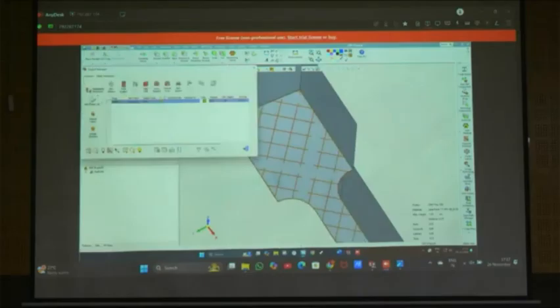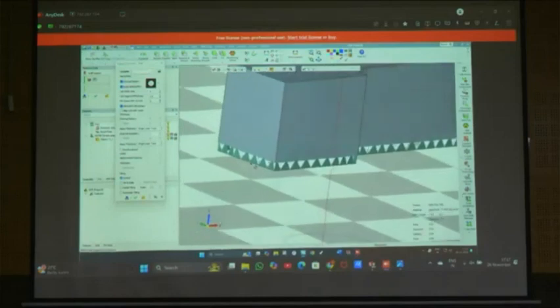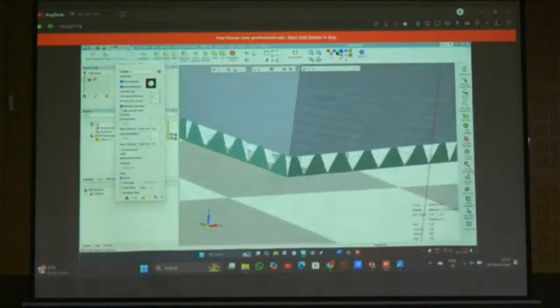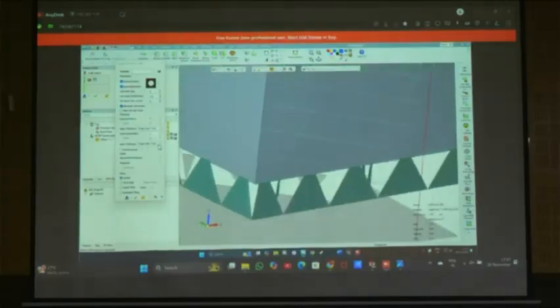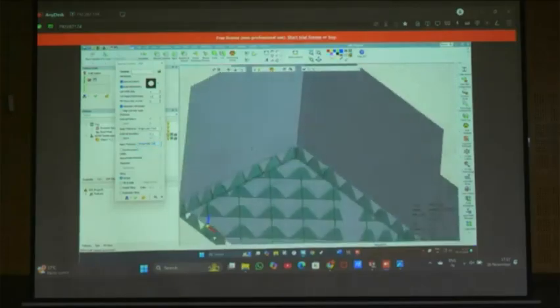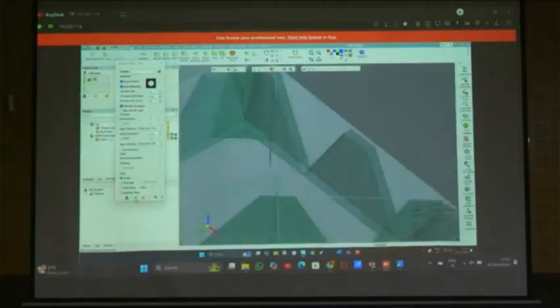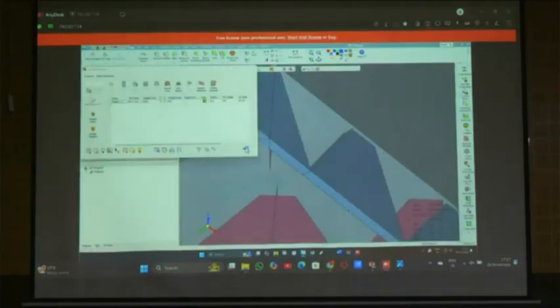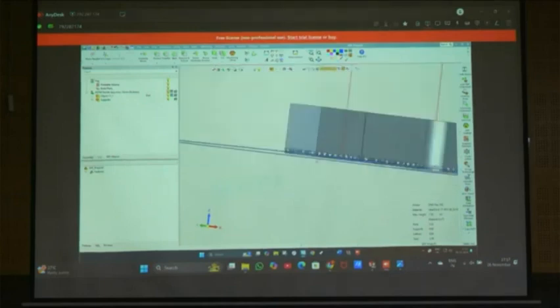Now we can go with the wall support. See, now this is what we are getting, right? But I don't want this to be a single thin wall, so I can keep this as create solid wall. Internally this is the thin wall, and the outer body it will create the solid wall. Now these types of supports we can easily break with pliers also. Pliers are a post processing tool. There is no use of wire cut EDM here. We can use pliers and remove it.